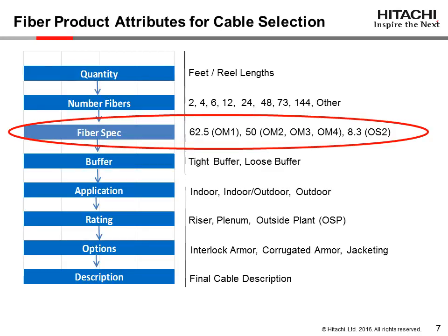The third, and one of the most critical product characteristics specified, is the optical fiber type necessary to operate the network. The specifier will first call out the core/cladding dimension, then followed by the fiber spec performance rating, i.e. 50 per 125 OM3. It is almost always a universal requirement that bend-insensitive fiber is included in the callout. Many times, the glass manufacturer will also be specified, i.e. Corning ClearCurve bend-insensitive fiber, 50 per 125 OM3.